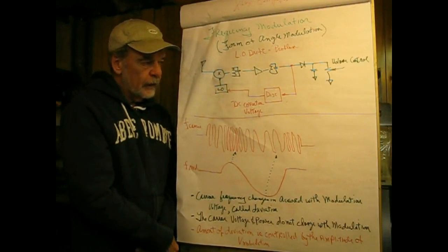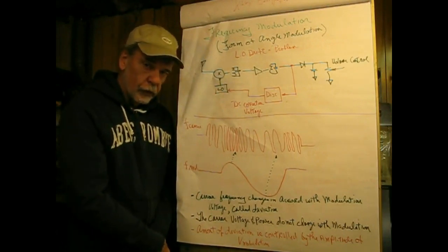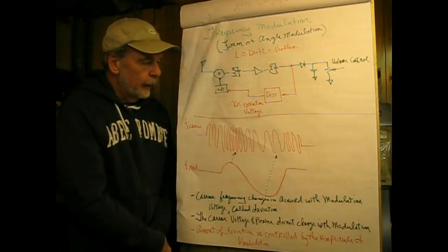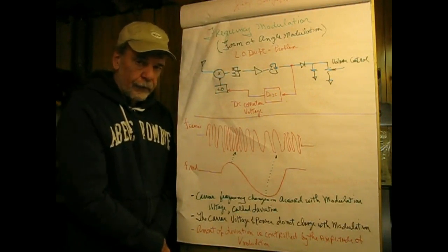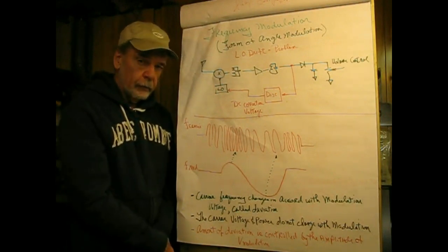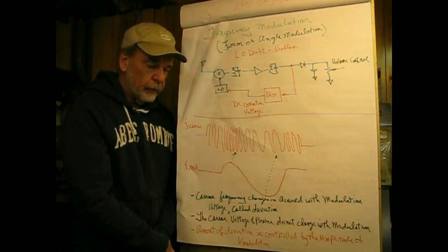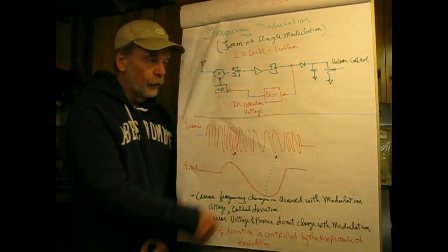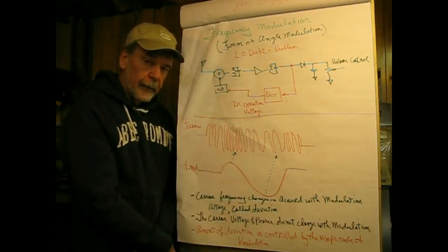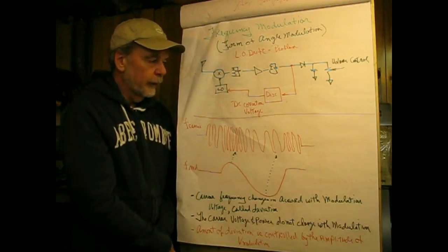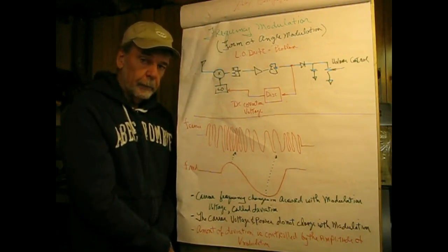This is the same as cruise control, which I used as an example before, a form of negative feedback. Will it bring the local oscillator back exactly on frequency? No, it can't, because if it did, there would be no error voltage for it to work with. But it works well enough so that you don't have to get up and retune it.